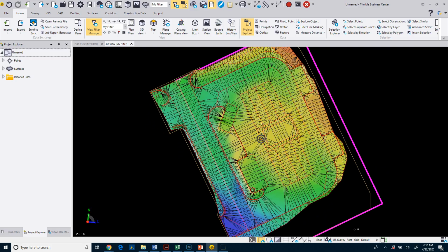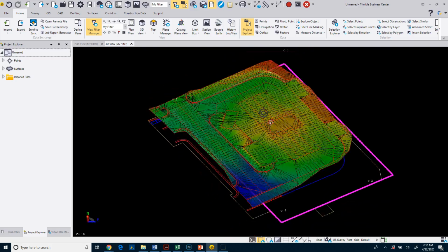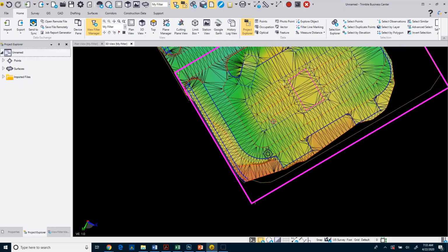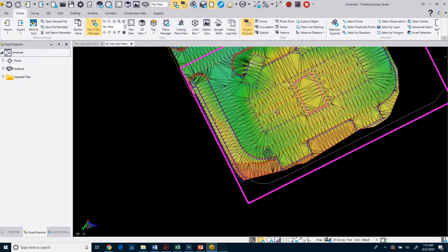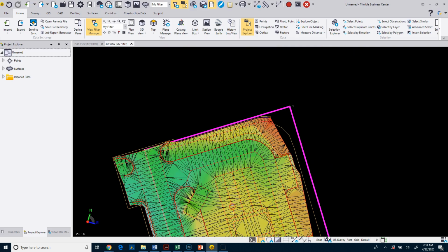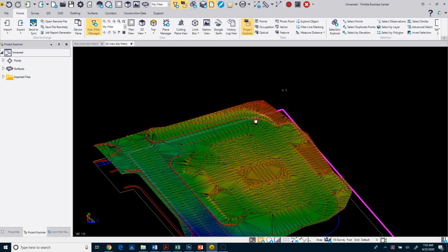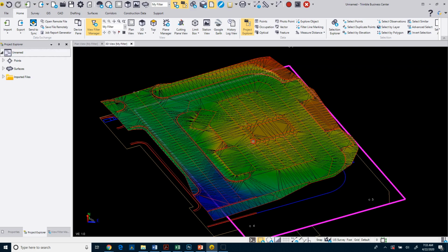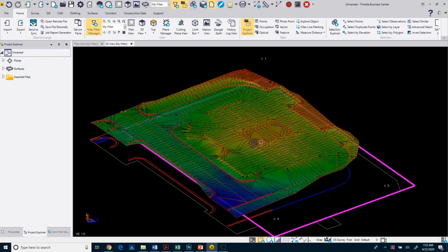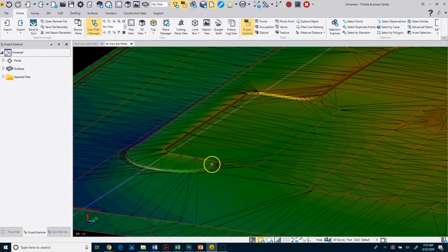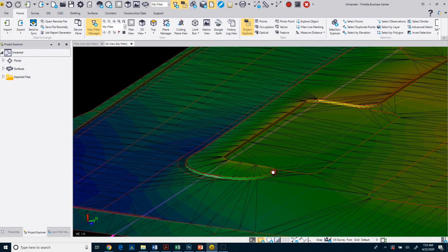If you rotate this and I rotate it all the way around, you can see that my 3D view will actually be possibly upside down, okay? So you can also use your right mouse button, hold that down, and that does a pan. So I can orbit, I can use the wheel to zoom in, and I can right click to pan.